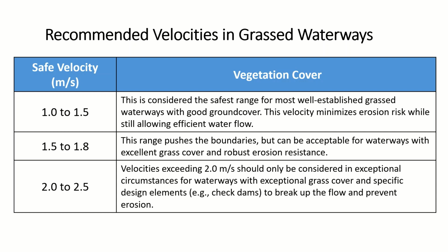So 1 to 1.5 is safest, 1.5 to 1.8 is acceptable. A little more than this may not be totally safe. But if there are check dams on the way, then it will help in reducing the velocity and preventing erosion to a certain extent.